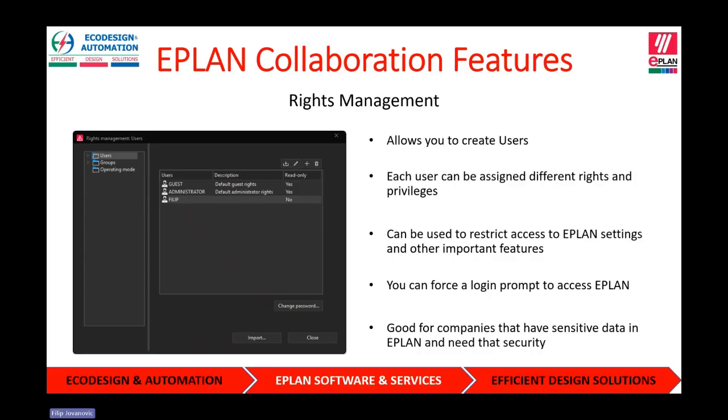So the rights management. What this does is allow you to create your own sort of login system for when you access EPLAN. And here you can manage which user accounts can access EPLAN. You can manage stuff like passwords and user rights. So once you've created your user, you can assign specific permissions, who gets to access what, or who will be restricted from what. This is really good for companies where you have a lot of sensitive data and you need that security.